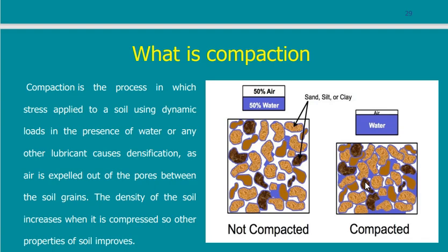It will act as consolidation, because I now want to expel the water. Expelling the water does not depend on the load only. No, it depends on the load, and it depends on the permeability, how water is going to leave this site. It needs to have ways and paths to go through.